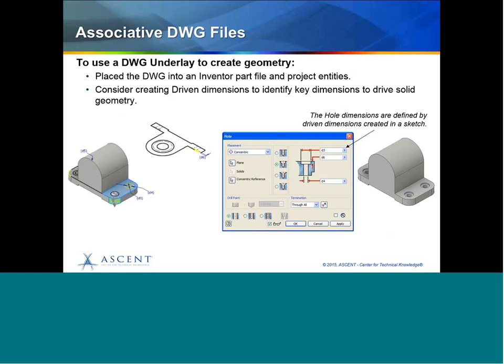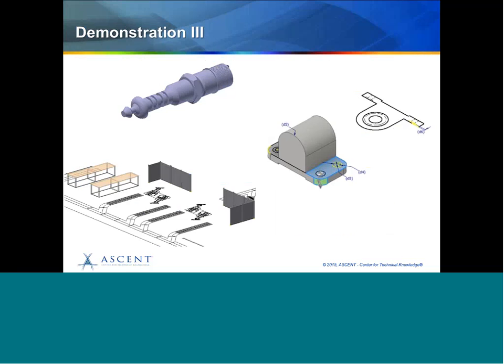Another application that I could see customers getting excited about is straight model creation. Here is an example of a little part where I've used the layout or the drawing from AutoCAD, and I'm creating model geometry directly in Inventor. And if changes are made in AutoCAD, I can then see those changes reflected inside of Inventor. So I'll show a little example of that as well.